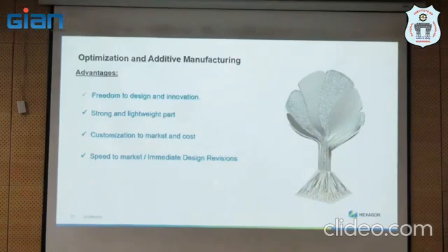So you may ask, what is AI based? We have been calling it AI based optimization. It is an algorithm written. In this case, we have written an algorithm saying that any surface less than 45 degrees needs to be avoided, so that my support structure can be avoided during printing. Then anything less than 0.5 mm is difficult for aluminum material. So I will write an algorithm saying don't optimize any wall or any part less than 0.5. Then it will use the algorithm, scan throughout, and optimize in such a way that my wall thickness is always higher than 0.5.